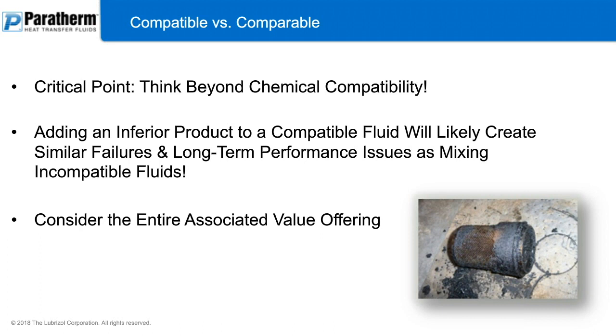One of the first claims that you'll ever see in thermal fluid competitive situations is, "Yeah, the fluid that you have in there now, our product is compatible with that." Well, it may be compatible chemically, but look deeper. If it's inferior, if it's got quality issues, if it's not the same design, if it's not as engineered, not as high superiority a fluid, it can still create similar failures as if it was incompatible.